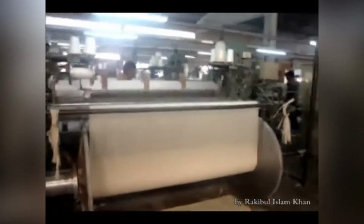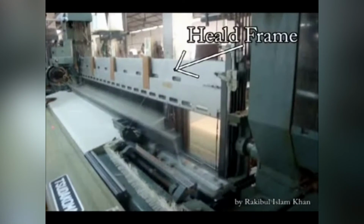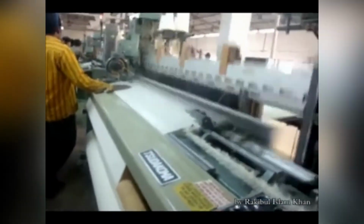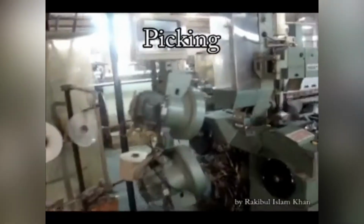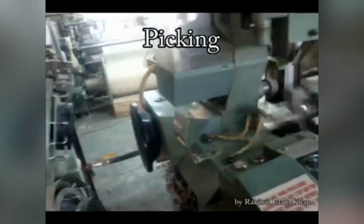Loom is the machine by which the warp yarn and weft yarn are interweaved at a 90-degree angle to form the woven fabric. The heald frame moves up and down to create a gap between the warp yarns according to the design pattern. This movement is called shedding. The weft yarn is passed through this gap at a 90-degree angle. This process is called picking.